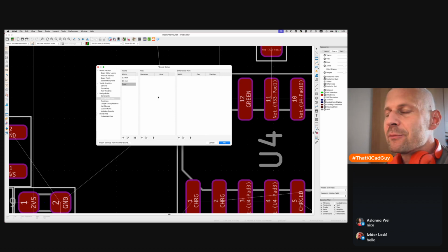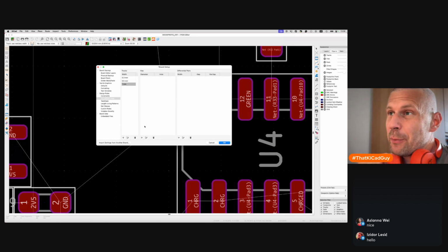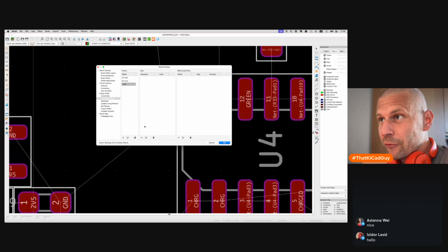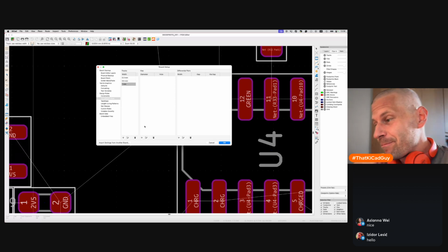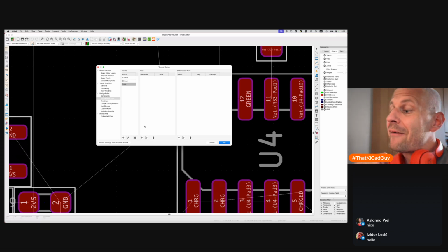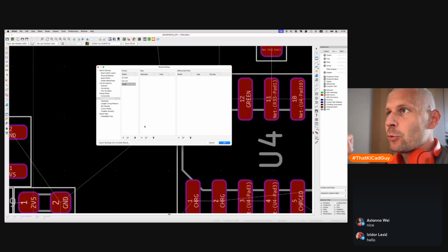Usually for dense boards, I use vias with 0.45 outer diameter and 0.25 drilling, but this time there is enough space, especially on this board. This board will be used as, not a prototype, but not a final design. I will tune the design, I will play with it, I will even change the circuitry. I hope I will not, but there is a possibility. So there is quite enough space in between components, so I don't need to make the vias so small.